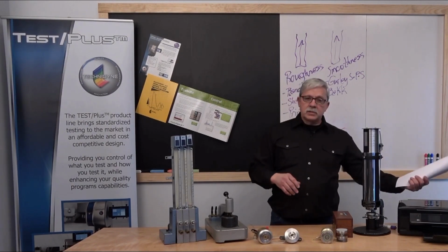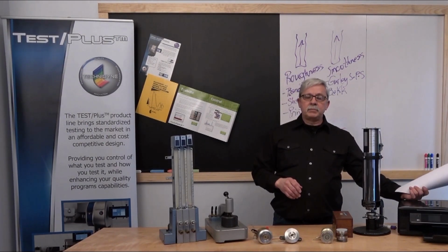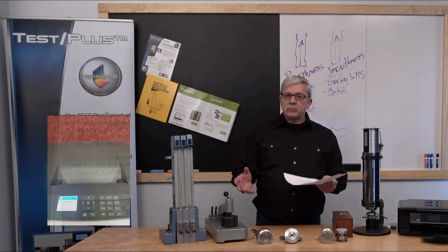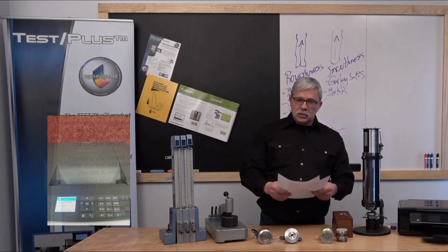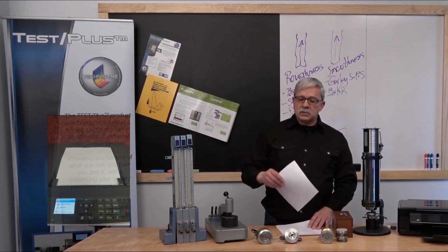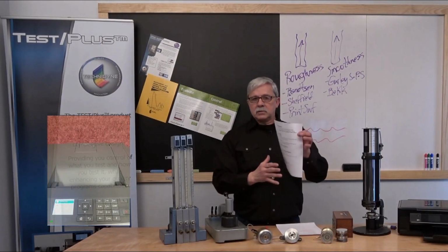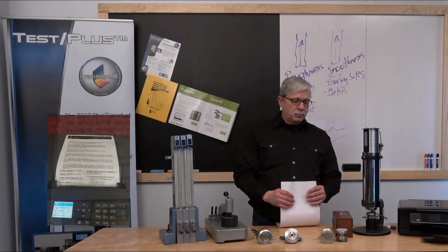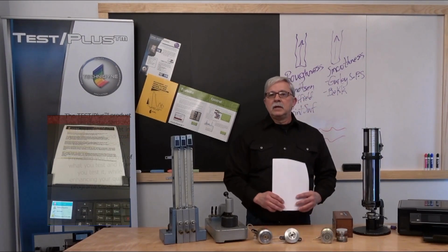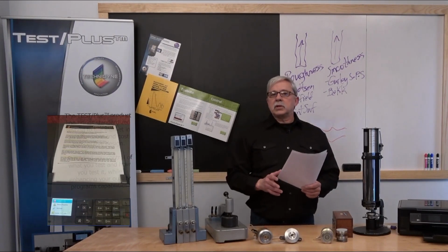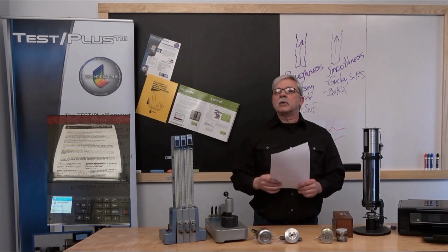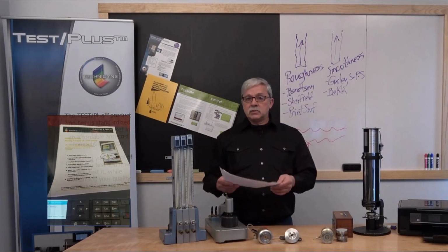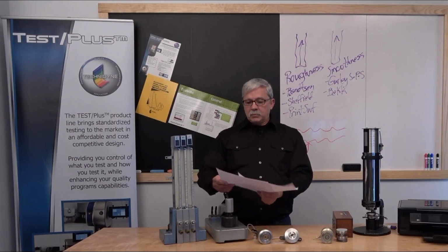So when we insert a ream of paper into a copy machine or a printer, and we hit that return key, hit that print key, we expect that one sheet is going to come out at a time, be fed through the print process, and come out looking something like this. All right? If the surfaces of these sheets that we put in here, the ream of paper, do not reach a particular smoothness or roughness value, we have an opportunity for these two sheets, in some cases, to actually pull out and have multiple sheets come out at a time.